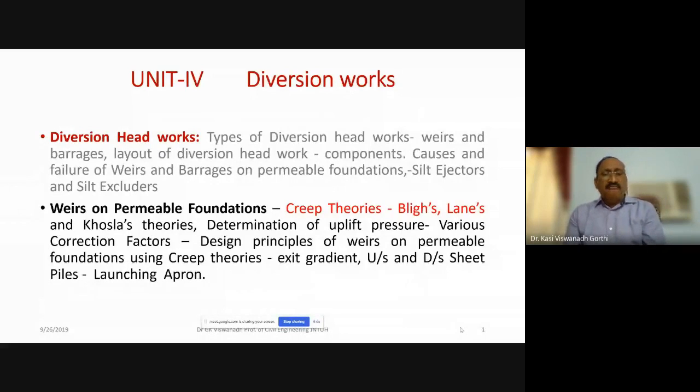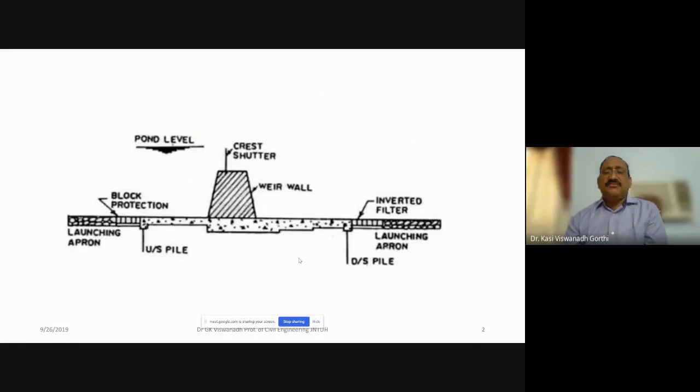So today we will be taking up weirs on permeable foundation and creep theory: Bligh's, Lane's and Khosla's theories. All these theories are for determining the uplift pressure and the thickness of the floor to be provided on a permeable foundation.